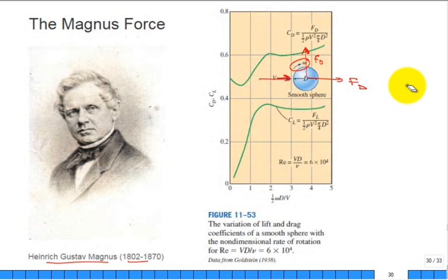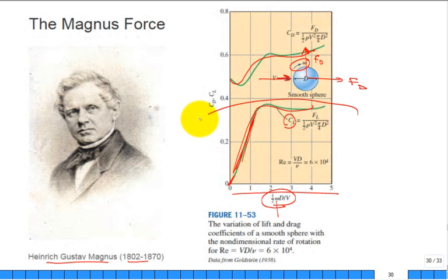Okay, so here is the lift force as a function of how fast it's spinning. There's the omega in there. So if there's no speed, it goes to 0. But then it's starting to spin, and you'll get increasing lift that's pretty straight right in this region, then goes out. If you can spin it faster, you get more lift. All right, and then this is the drag. The drag is affected by the spinning speed, but this is the most important, the lift. This is a very old data plot from, 1938? Some old data.